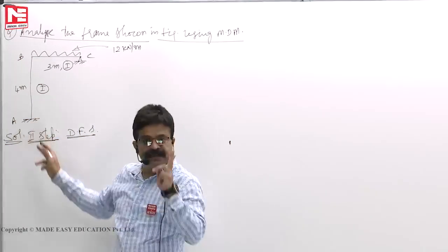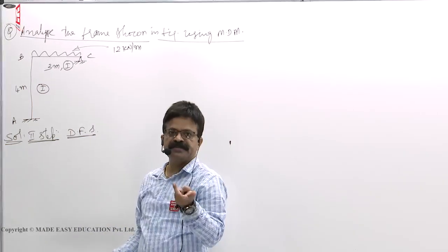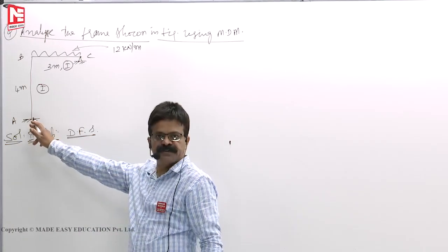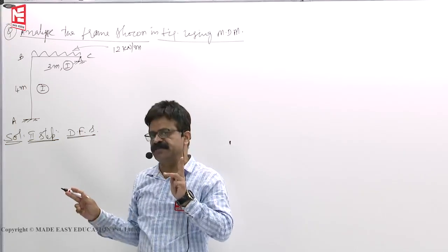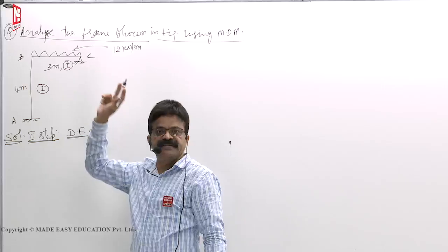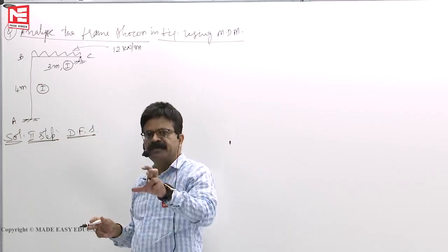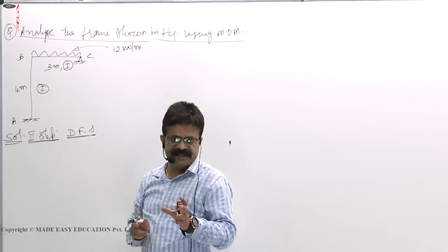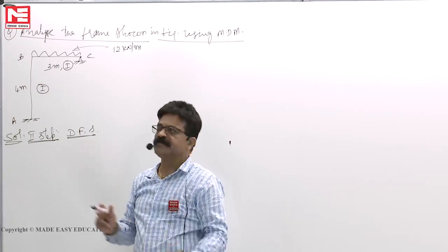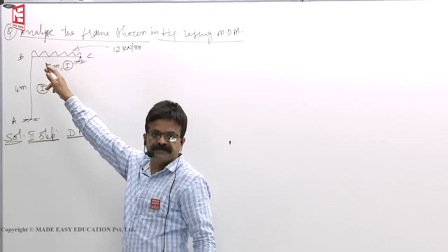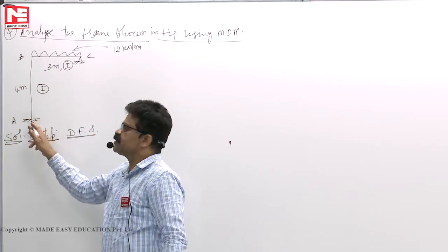So here at A there are two members, footing and column AB. At B also two members. This we call a fixed support, meaning the slope is 0. Two members are meeting but slope is 0. At B we call it a rigid joint. BC and BA, two members are there. But when you apply moment, these are relatively comparable stiffnesses only. So when you apply a moment, both will share, because now the distribution factors will come. So we call it a rigid joint. The difference between rigid joint and fixed support is only that.